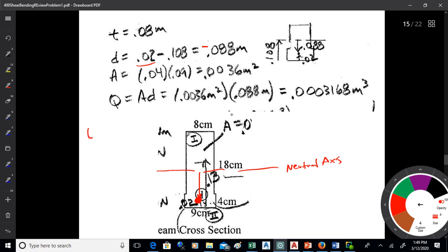So what I got for tau, and that's it. Is that B1? Is that correct? B1? Yeah, okay. And I got 1.28 megapascals. And we'll look at these tomorrow, but see if you can get these figured out by tomorrow. And then sigma, compression, and this is max, okay? And then we've got sigma T max. They're slightly different. The compression, I got 163 megapascals.